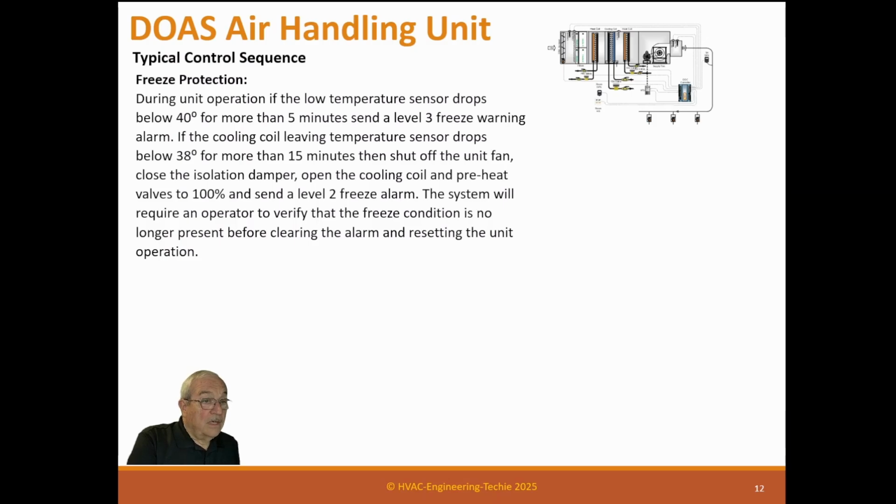Now, normally this would happen if the preheat coil failed, if the valve failed closed, or if the hot water is not working or the pump failed, then we would see that freezing air come into the coil.